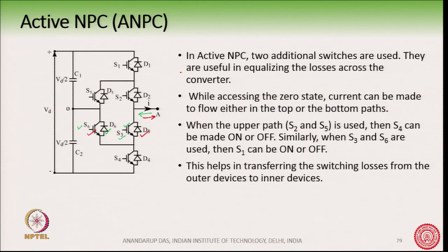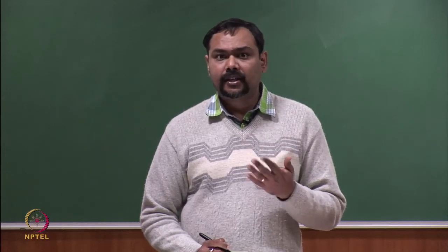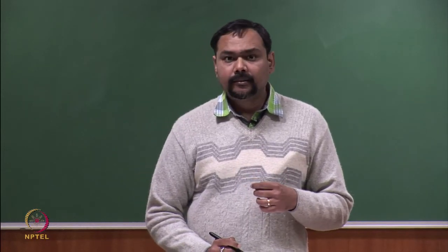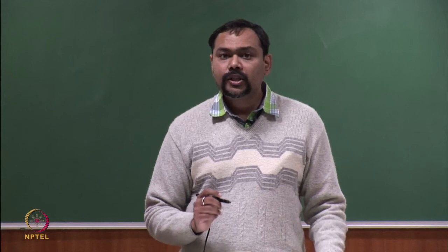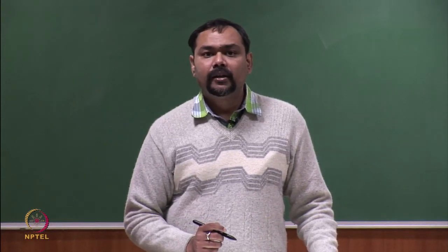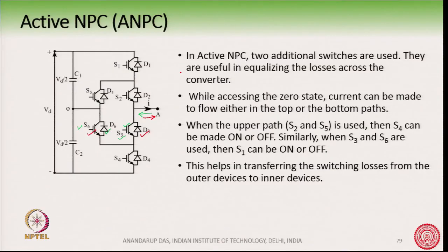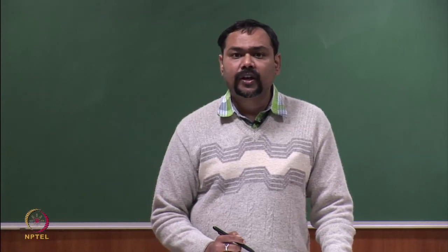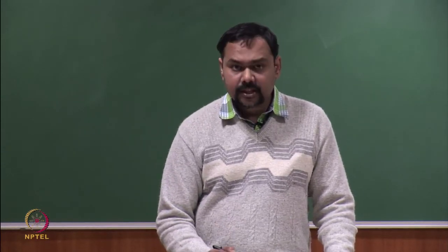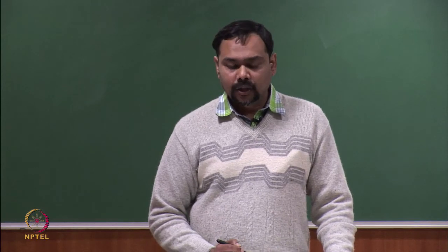Why do we do that? Because next time after the 0 state, if I want to switch on the plus state or the minus state, then the switching losses can be minimized, or I can say the switching losses can be transferred from the outer devices to the inner devices. Okay.